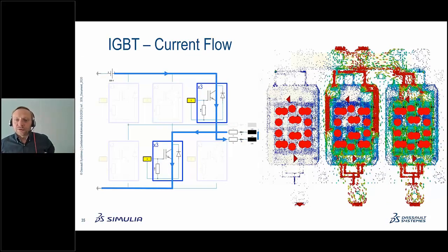And then we can, of course, use our nice combined results feature that we have introduced to you and look, for example, at the different phases here. So this is the phase where the DC current comes in over the W phase, flows through the motor and goes out over the V phase, and that's exactly what you see here. So this is the current back, so this is the V phase. The current flowing from the DC plus is going here, then over the bond wires down here. The motor itself is currently modeled in a very simple way.